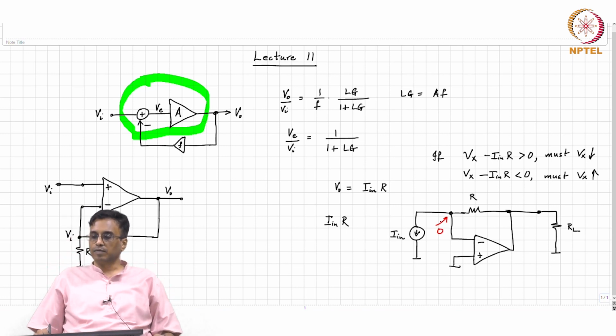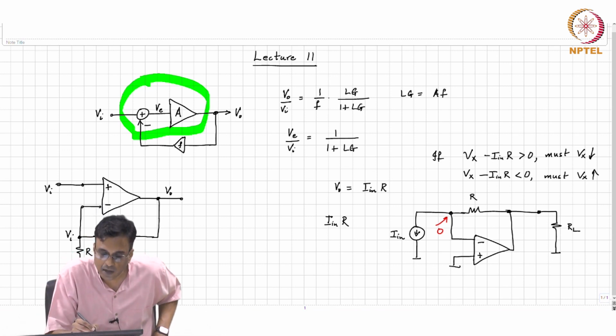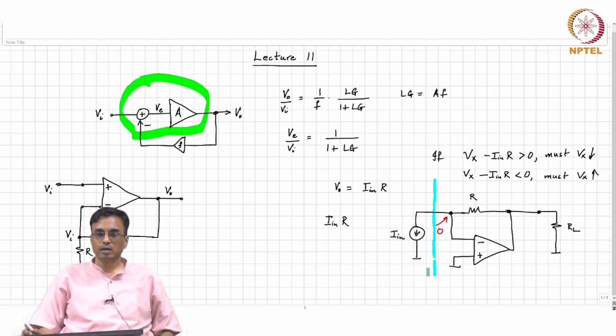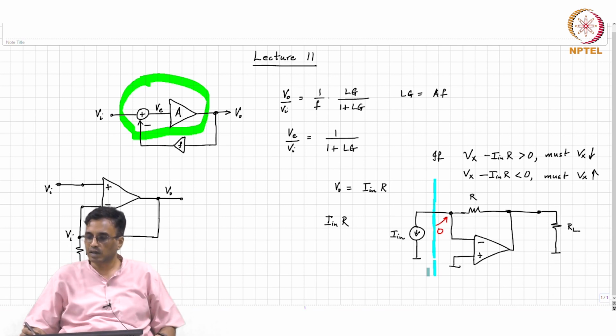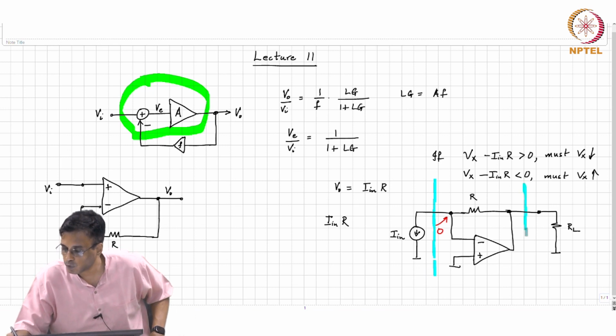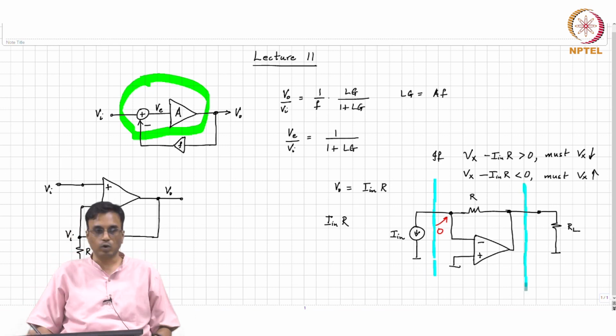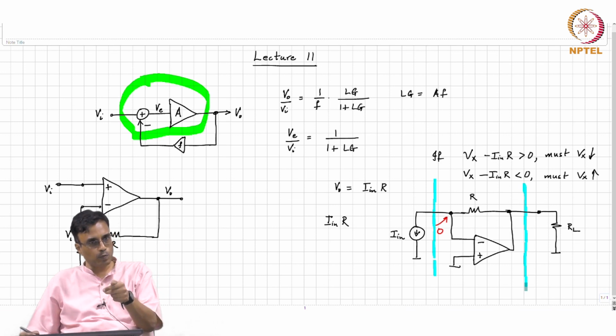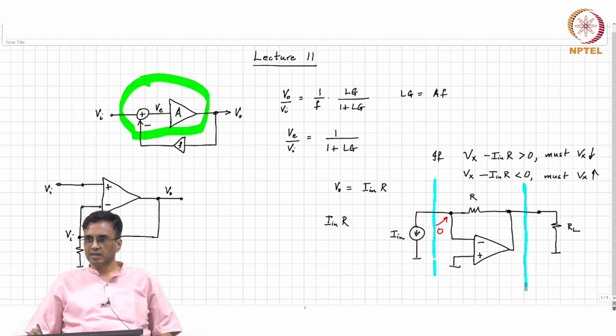So, therefore, what is the input resistance looking in here? What is the input impedance of this? So, this is our claimed voltage controlled, I mean current controlled voltage source. What is the resistance as seen by the input source? 0. Why? Because that voltage, regardless of how much current you pump in, the voltage always remains 0. So, the input impedance is 0.